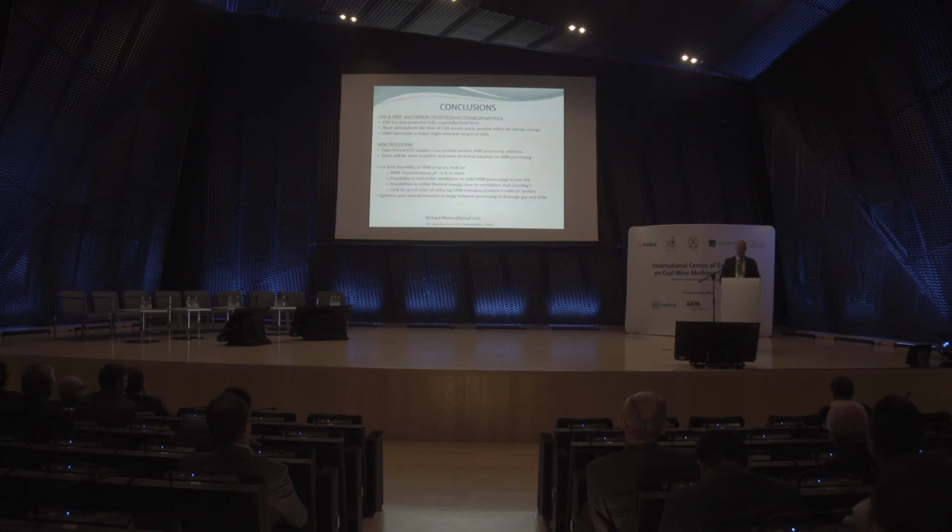Now, for the best feasibility of a VAM project, you should look for VAM concentrations around 0.5% or more. You should look at the possibility to enrich the ventilation air, where you can take drainage gas and feed it into the ventilation air for the purpose of reaching 0.5%.